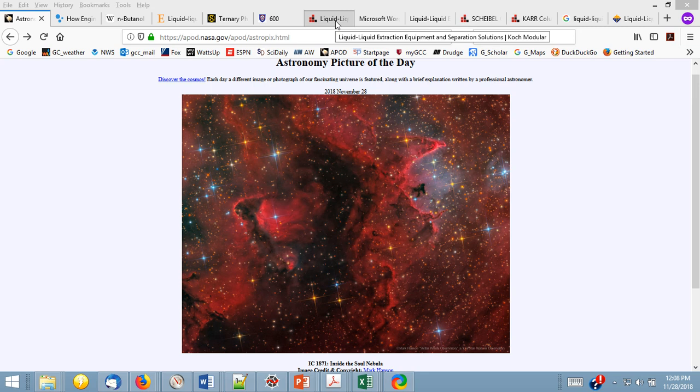It turns out that in a lot of cases for separation processes that use liquid extraction, the actual contactor for the liquid portion really represents a small fraction of the overall system. Because usually after you've carried out a liquid extraction, you have to do further separations to recover the solute from your solvent and so on. And that equipment is going to involve distillation, stripping, etc., depending upon what you're doing.